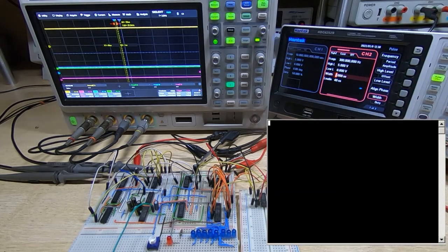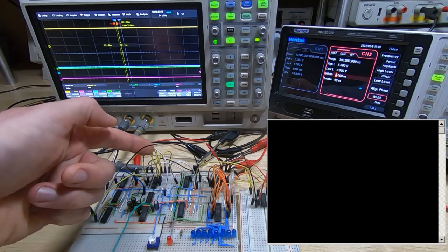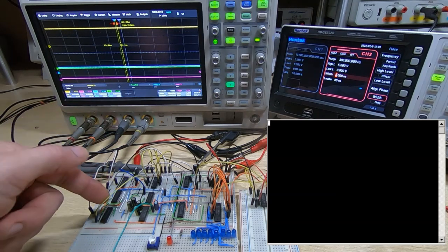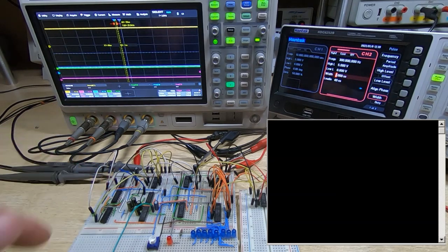The main clock is already on, and what I will now do is enable the second channel on the signal generator, and it's just going to provide a series of low-going pulses that simulate the Z80 trying to load and send data out of our RS232 port. If you recall, we start the process by taking the start line of the transmitter circuit low, and at the same time we provide it with a data value. The data value at the moment is provided by these yellow jumpers, and it's easy to change just by fitting or removing this jumper.